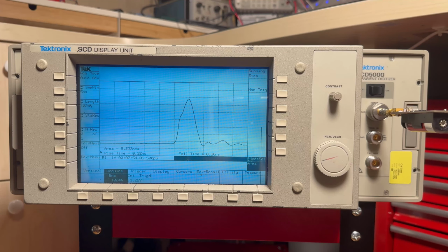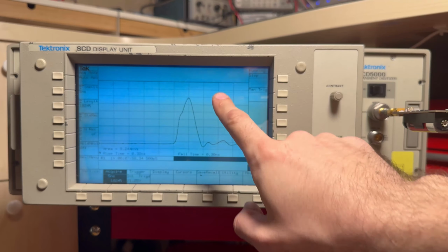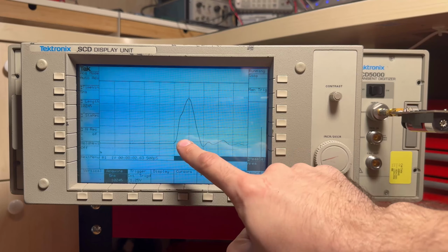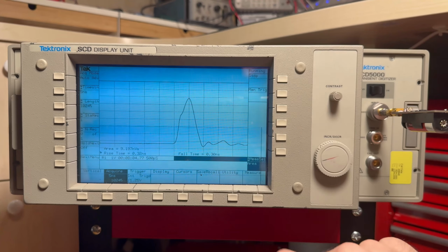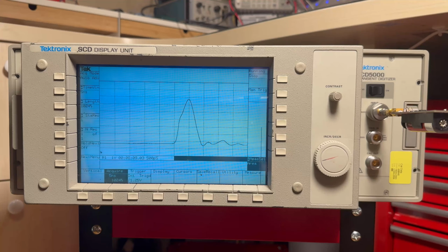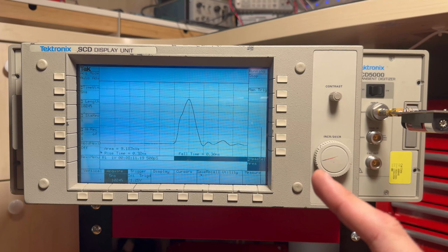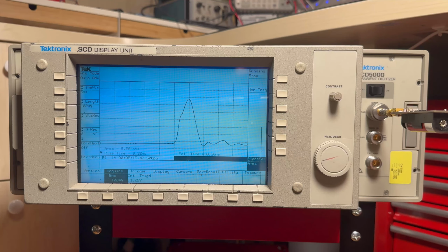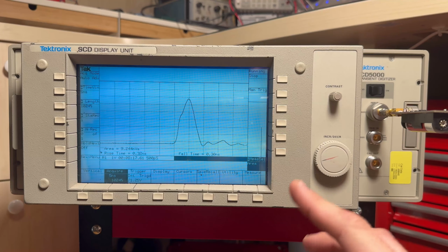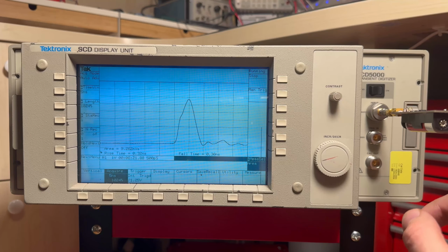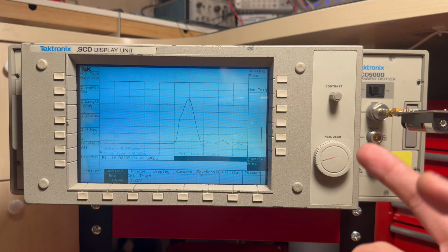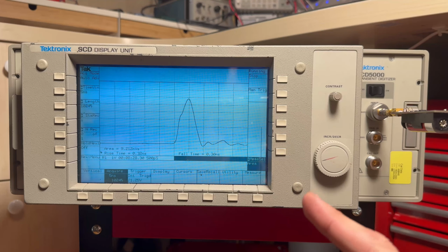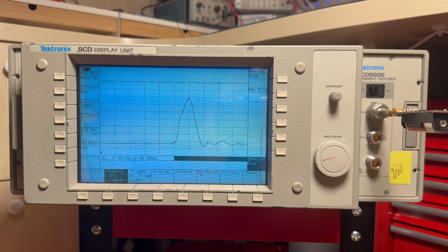And you can see that basically the pulsar has 2 rise times almost. So there's a faster one here, and then it settles out into here. The fall time is oftentimes faster than the rise time. And as I've confirmed in the previous video with the Tektronix MSO4 series, the 1.2-ish gigahertz that I saw was the limit of this thing here, not the scope. So this kind of agrees with the rise time measurement with my 7104. Yeah, it's insane, absolutely insane. And the fact that it works, I've never seen one working, displaying anything, not even on TekWiki.